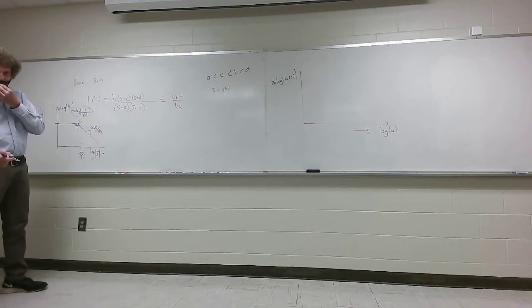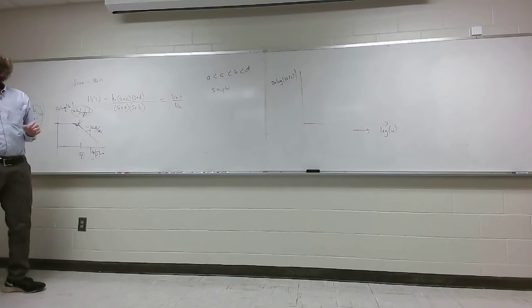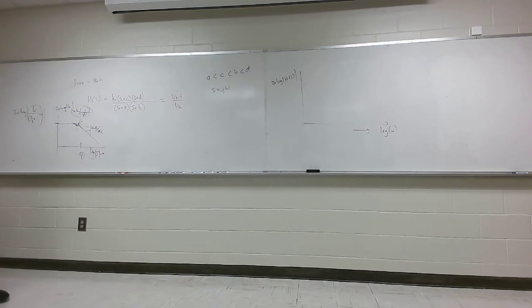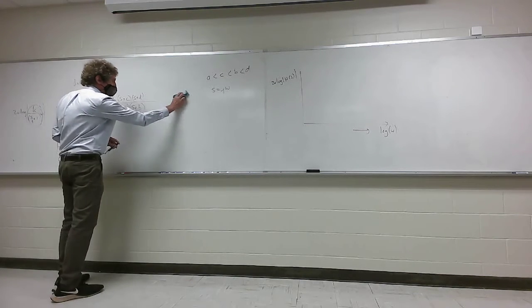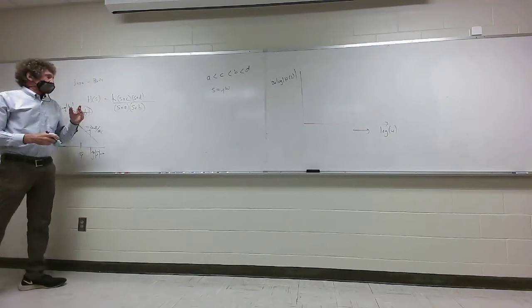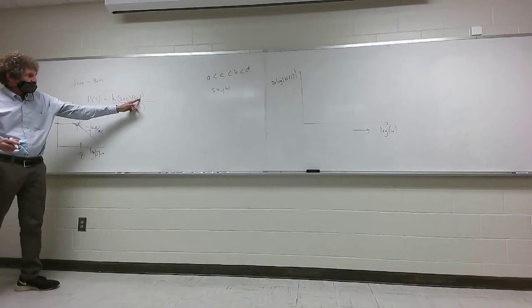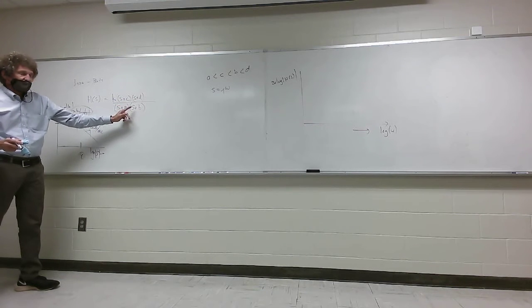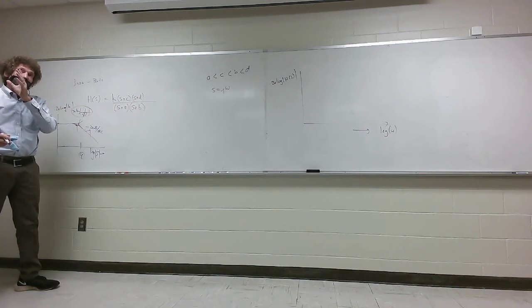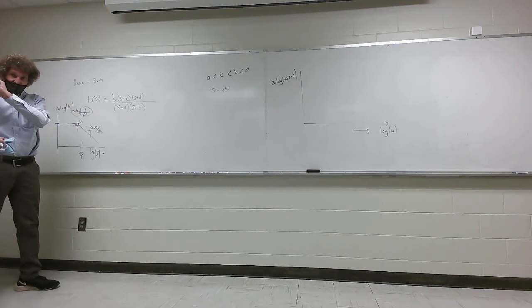Back to this thing now. So what I have to do, and here's where I slow down, make sure I make my point. You don't just brute force this function. What you want to do is have all the coefficients here inside these S plus A, S plus B, be S divided by something plus 1. Do y'all follow me on that, class? This is real important.